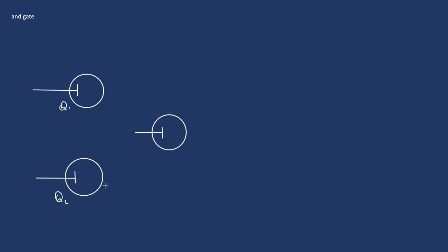This time around, we're only going to ground Q2 and Q3. So that's the output transistor. These are the only ones we're going to be grounding. Okay, so these guys are coming to ground this way and that way, and we can draw a ground connection. So that's always a good place to start. Which of your transistors are being grounded? If you've drawn them in the right orientation, then you can get right into doing that.